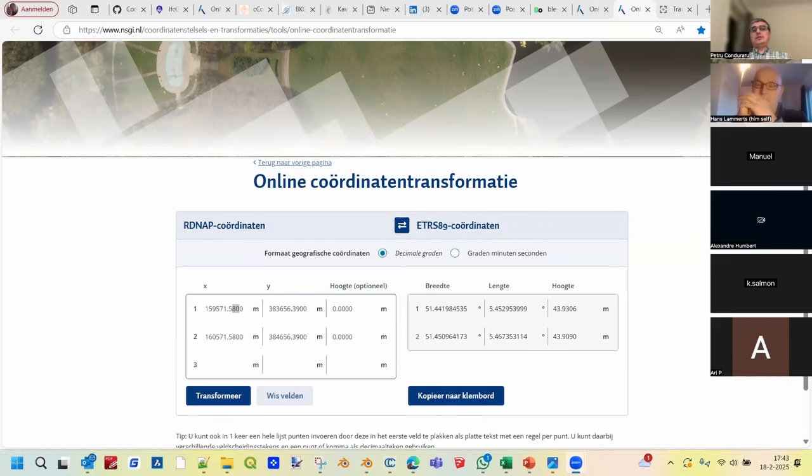Yes, it's fixing it. It's a little bit intelligent. It first reads out if there is any geospatial reference already in there. It will notify you if it's there and point it out to you so you can check it. If it's not there, you can choose two points or one point to get that into the IFC data.